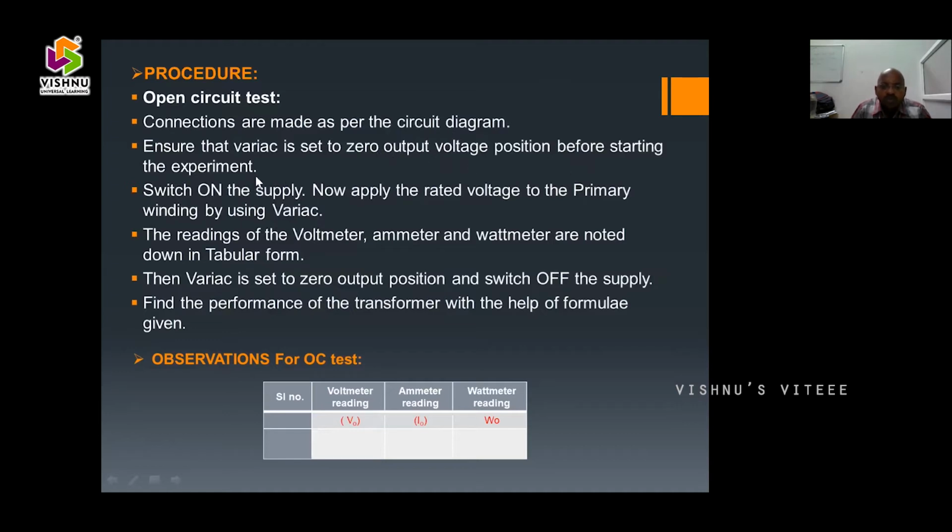Before starting the experiment, you have to take some precautions with each and every component. You have to keep the knob of the variac at zero position, and all meters should be at zero; the pointer should show zero reading. After that, switch on the power supply.